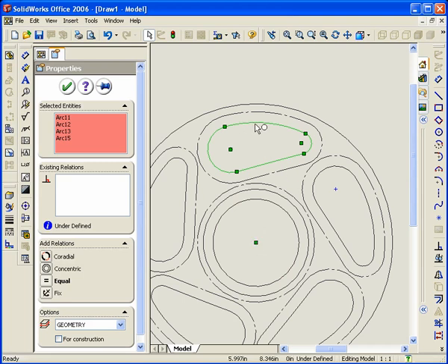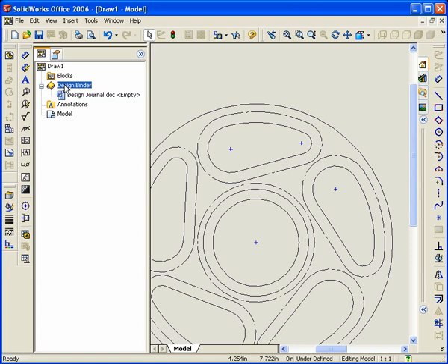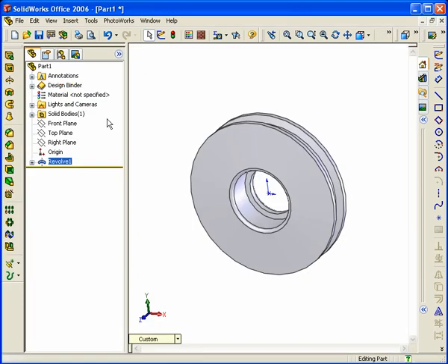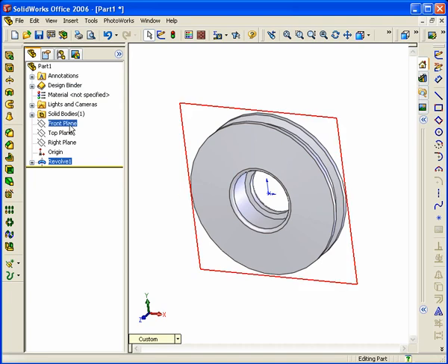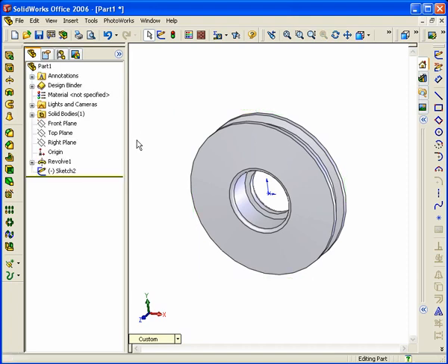What's nice about this design is that there's an outside radius that follows the center point, so we have a nice locator there. Again, you're not always going to have this with geometry, but here we go. Next step is to hit Control C to copy it. Then hold down Control and hit Tab, actually hit the green check mark here first, and Control Tab will bring you back to the 3D model. Now we select the front plane and hit Control V to paste it.